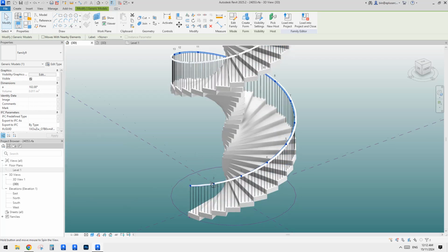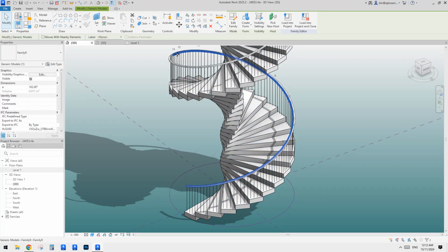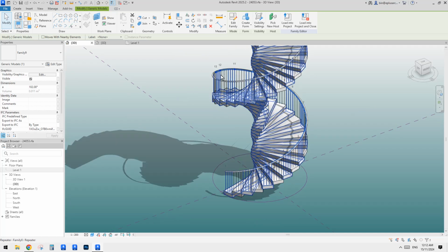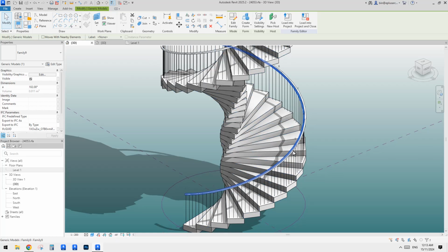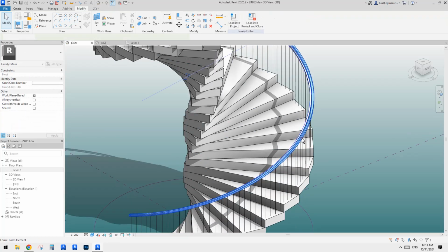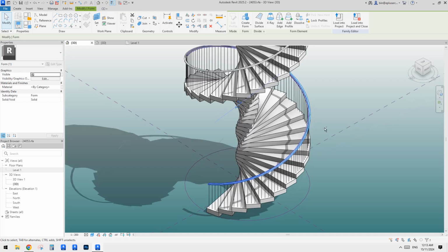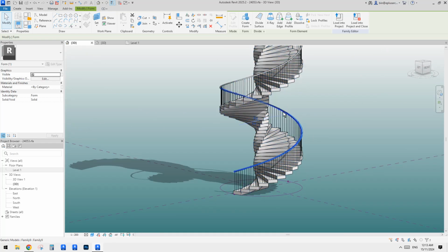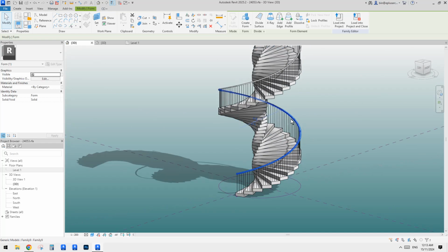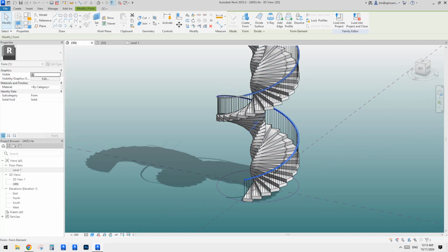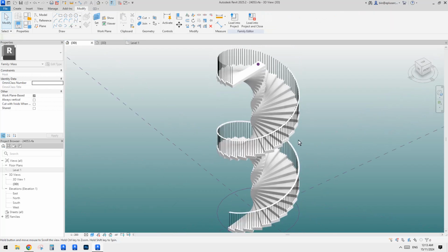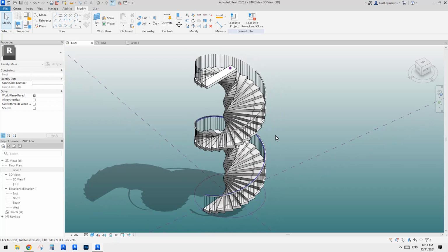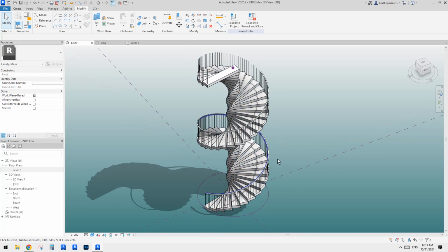We can add an angular parameter to rotate the railing profile, one of the railing profiles. Another method is we can also model in place, using the blend style form, using a half circle profile and another profile to create one segment of this railing, right? And then create another one. So yeah, this is it. I can upload this one so you can have a play.